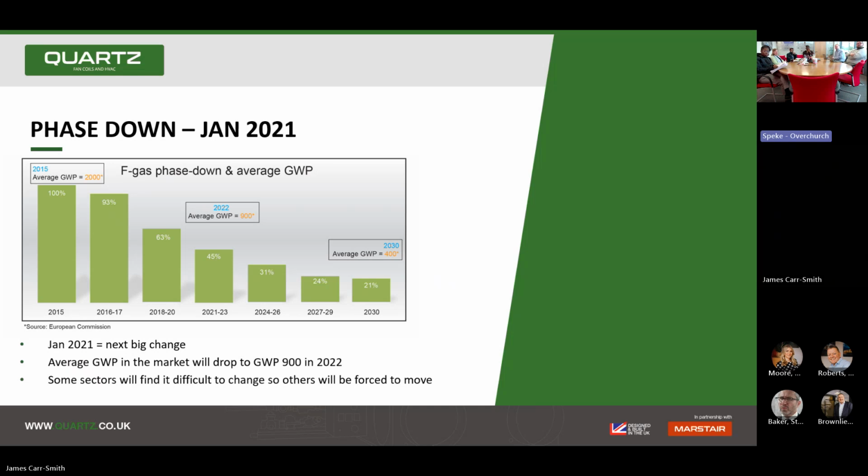Back in 2015, when the F-gas came in, it came in with the 2009 to 2012 average amount of refrigerant that was placed on the European market. So it started at this 100%. And then over the years, 2018 being the first, what was known as the F-gas cliff, suddenly lost 37% of the refrigerants on the market. We're now obviously in 2024. So as you can see, we're 69% down from where we started in 2015 in terms of the actual availability of some of the high GWP refrigerants.